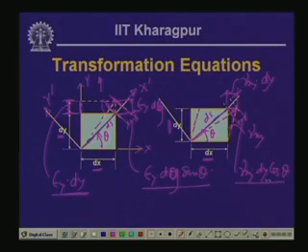So, we have three extensions of the diagonal obtained now. In the previous case where it was getting stretched in the x direction, we have the extension as epsilon x dx cos theta. In case of strain in the y direction, we have extension of the diagonal as epsilon y dy sin theta, and for the shearing strain the stretching of the diagonal is equal to gamma xy dy cos theta. Hence, if we look into the total stretching of the diagonal, let us call that delta d.